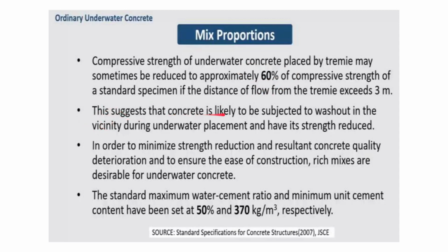So this suggests that concrete is likely to be subjected to washout in the vicinity during underwater placement and have its strength reduced. In order to minimize strength reduction and concrete quality deterioration, and to ensure the ease of construction, rich mixes are desirable for underwater concrete, because there is a chance of loss. Okay, so richer is the mix, better is the desirable value for